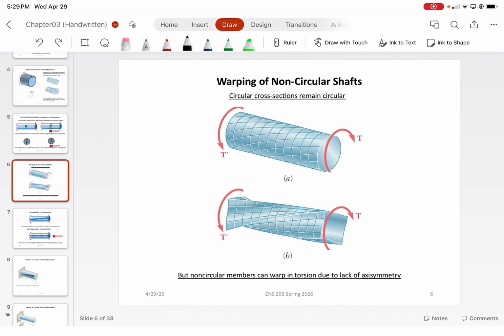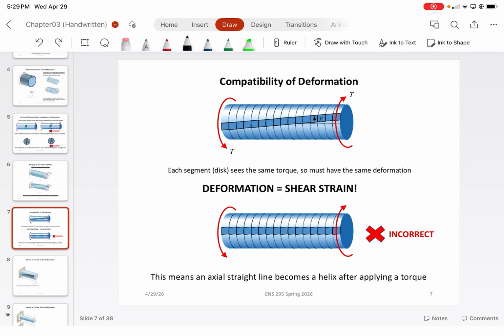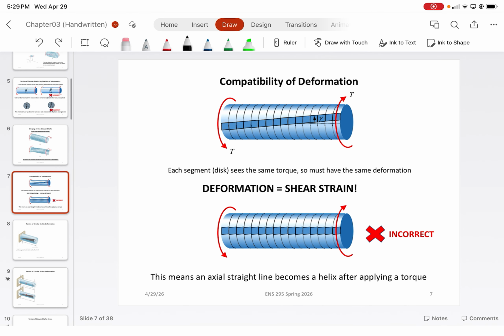So it's safe to assume that the radial deformation should be continuous. That's because if you're looking at some small area, like if you were to cut through for your section for equilibrium, the torques should be the same. The only thing that changes is just how much deformation it goes, but the angle of that deformation should be constant. And we'll actually get into problems later on.